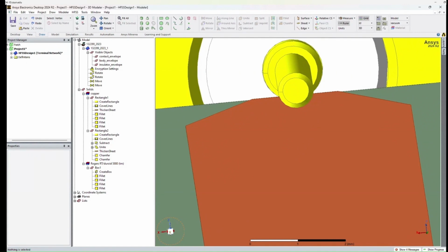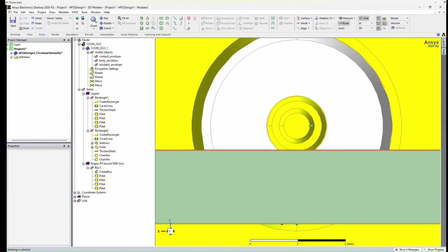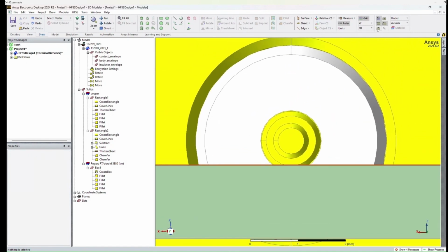Just go ahead and align your view to the face of the connector, so it's right here, and then deselect all of these except this one box right here that aligns your cursor to the center of an arc. These are just helpful cursor snap tools. And then change your drawing plane to the correct plane.